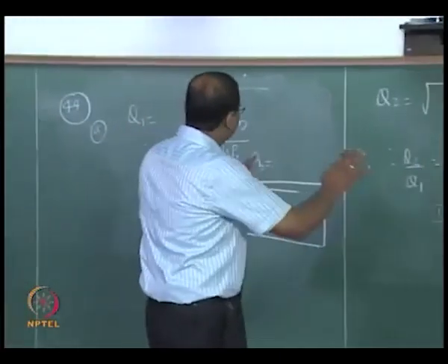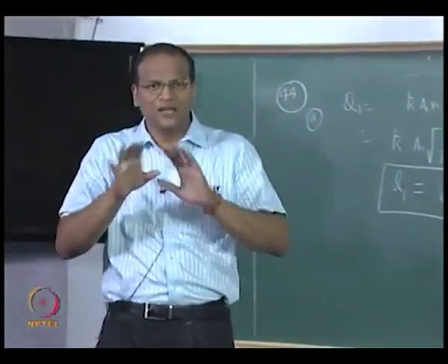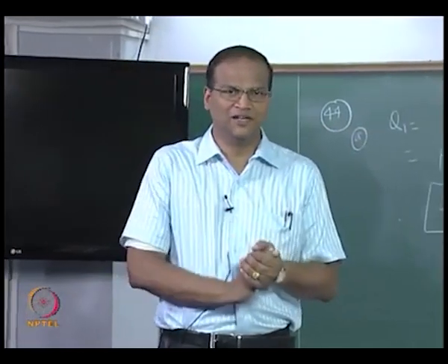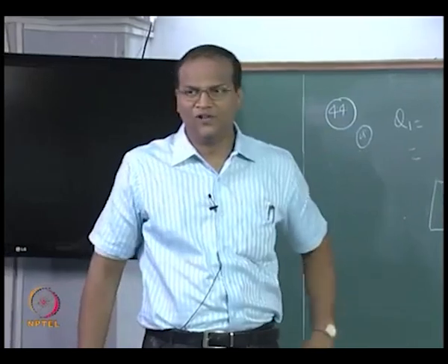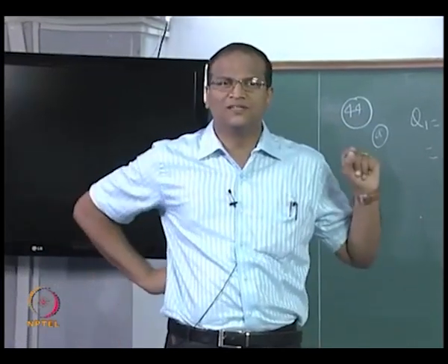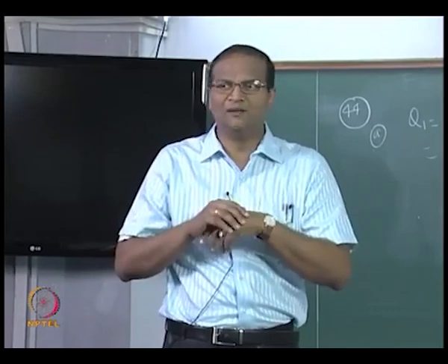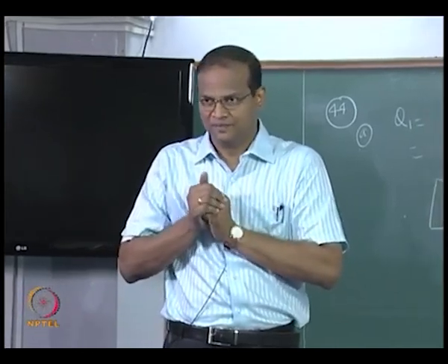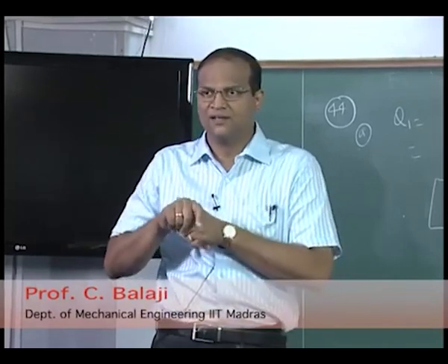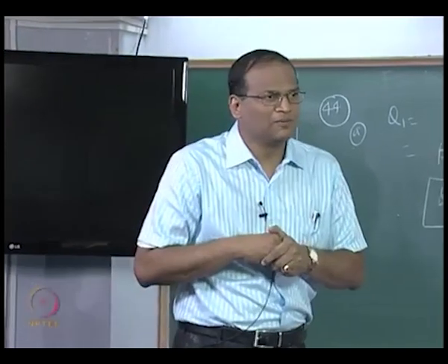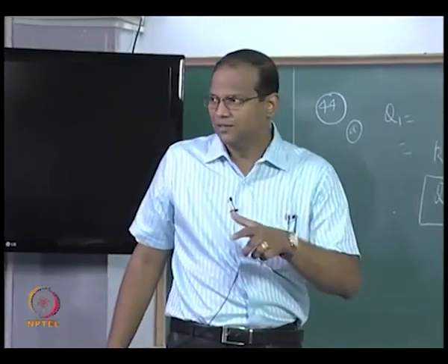Now you can see this sort of exercise gives you an idea of the basic heat transfer processes, how each of these parameters influences the heat transfer rate. So this gives you a good idea of the role of various parameters. I can also conduct some experiments where I have a long fin, I measure the temperature at 2 places, okay. Then I know that theta by theta b is e to the power of minus mx. Now I can solve it as an inverse problem and get the value of m. From the value of m I can get the value of thermal conductivity, right.